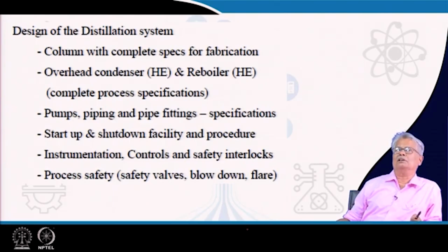You have to talk about and provide in the form of a P&ID the instrumentation control and the safety interlocks which are implemented through instrumentation, and definitely the safety valves or blow down arrangement and the flare for process safety, whatever is required for your plant, the distillation system has to be provided.